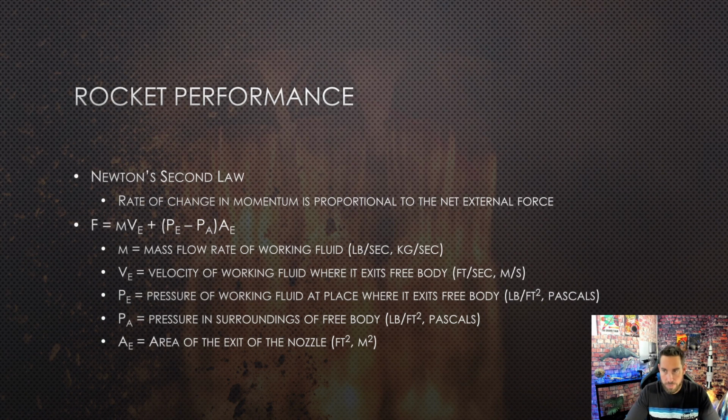All right, just a couple of equations. It's helpful to know what these things look like and what they'll govern. So rocket performance is governed by Newton's second law, which simply says that the rate of change of momentum is proportional to the net external force that acts upon the body.